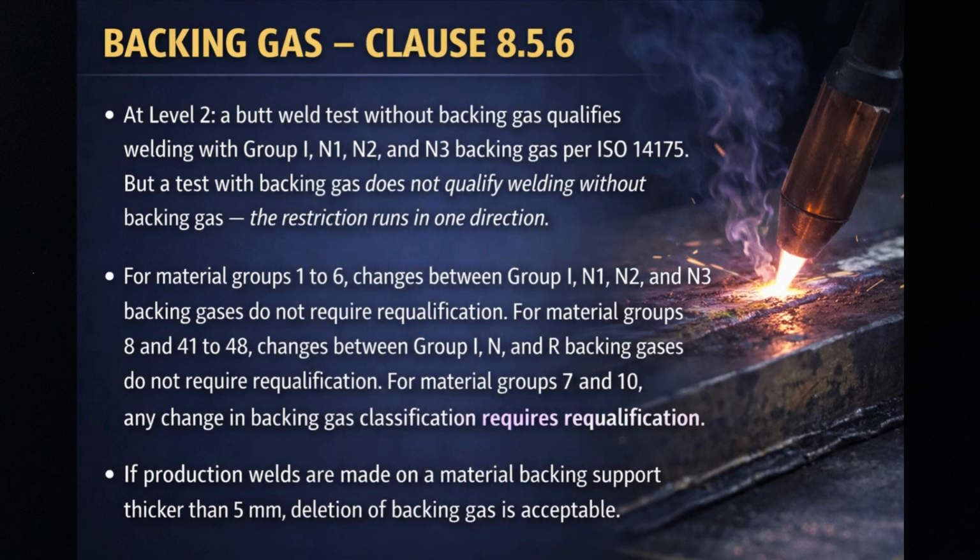Backing gas, Clause 8.5.6. At level 2, a butt weld test without backing gas qualifies welding with Group 1, N1, N2, and N3 backing gas per ISO 14175. But a test with backing gas does not qualify welding without backing gas. The restriction runs in one direction.